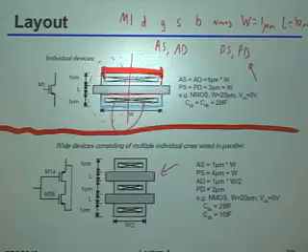Yeah. So your current flows both up and down. Yeah, exactly. You said exactly the reason we talked about, which is notice my current always flows both up and down. In other words, if this is my unit cell, as long as I don't rotate it by 90 degrees relative to something else I'm trying to match it to, then I'm basically guaranteed that I won't screw up my current flow directions when matching multiple different devices.